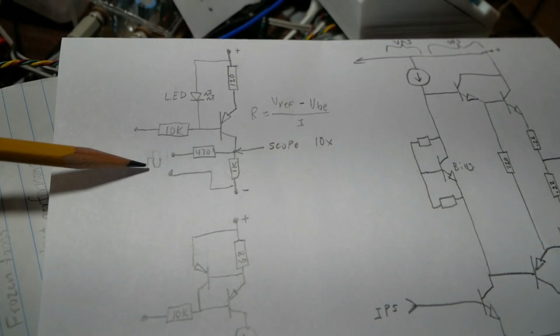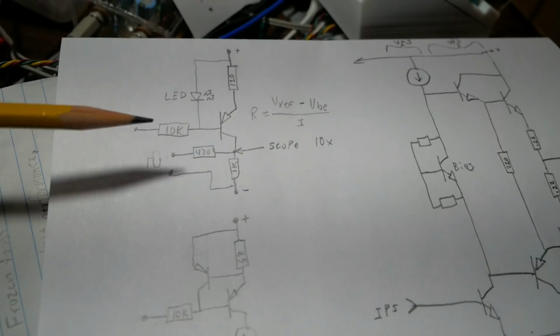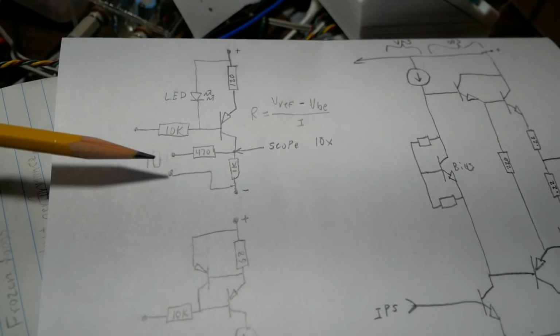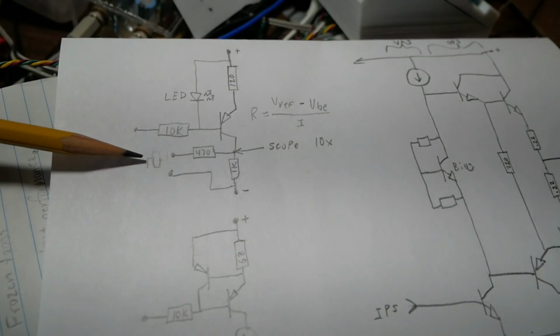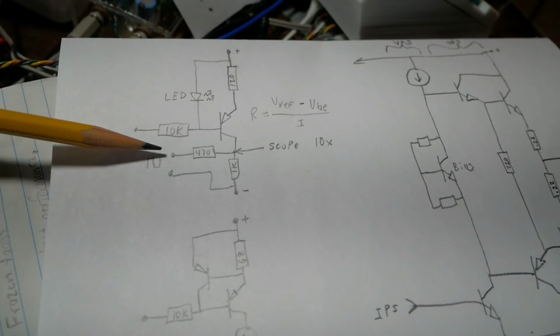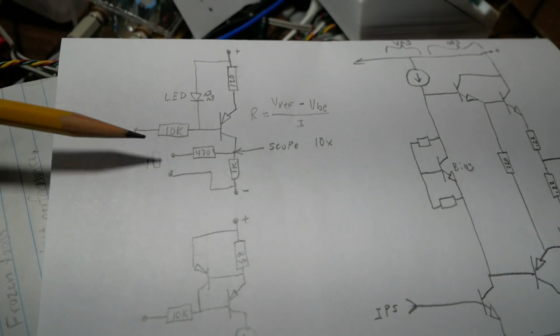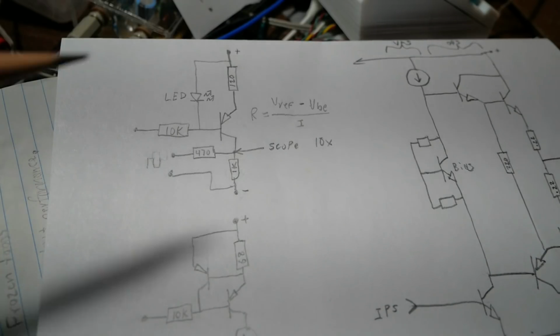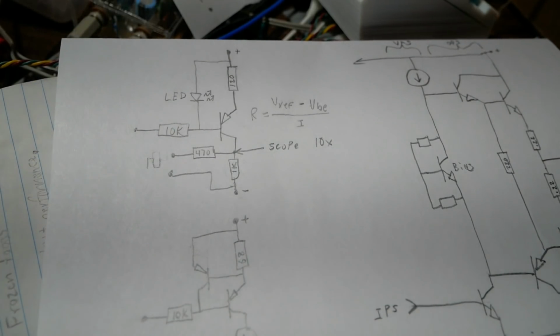Now you might be saying, doesn't your function generator have a DC offset that you could use? Yes, it does. However, to get the full peak-to-peak voltage I need to drive this with, I can't really use that. So I'm just going to send the signal along with some power supply voltage to offset the signal to keep this turned on during the full cycle of this waveform.